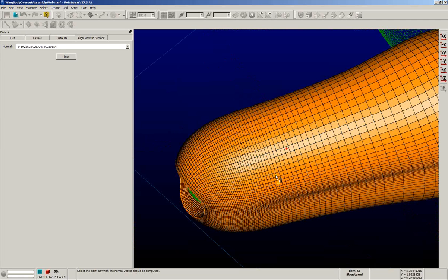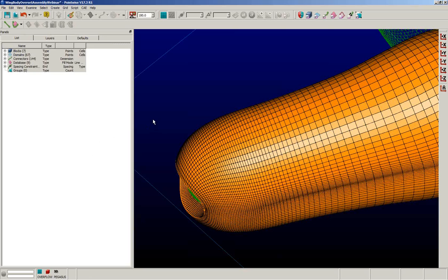So this is a nice new option that we've added for changing your orientation. It can be really handy for situations where you're trying to do projection of connectors or domains onto database surfaces, and say perhaps you'd like to use a linear projection style instead of the default closest point. You can use this to quickly and easily change your view so that you're oriented normal to that database surface or surfaces, and then perform your projection and get the results that you're looking for. So this is a cool new tool that we've added for changing your view orientation in 17.3.